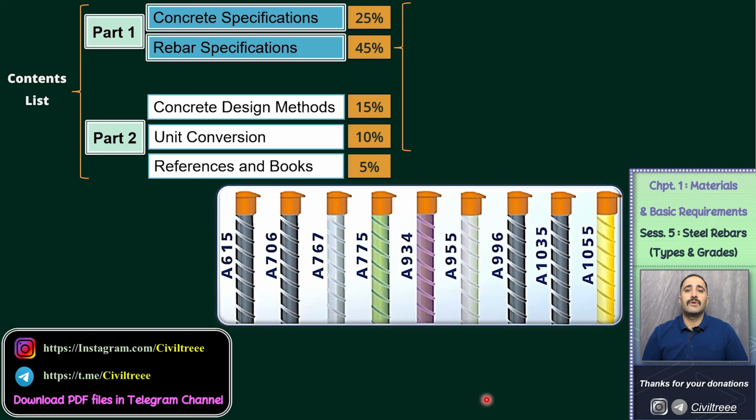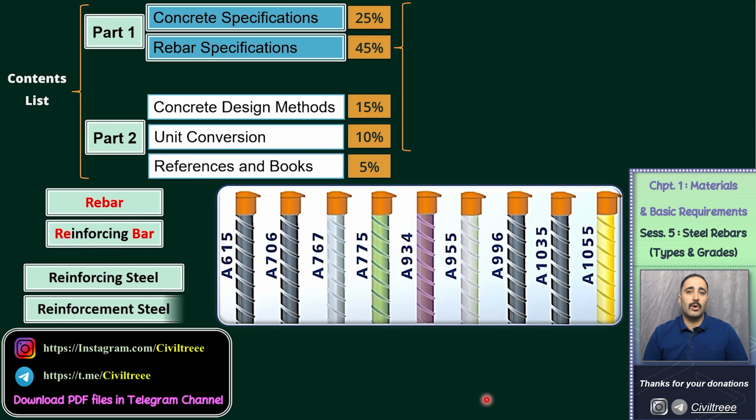In previous sessions, we talked about concrete specifications, and from this session onward, we will address the specifications of reinforcing bars. Rebar is the short form of reinforcing bar. It is also known as reinforcing steel or reinforcement steel. As you know, concrete is weak in tension, and we reinforce it with steel bars or wires to resist the tensile stresses. As a structural engineer, you specify the type, grade, size, number, and even location and spacing of rebars.